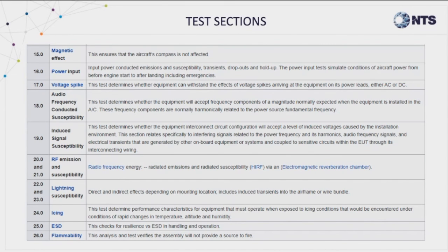I apologize. Is it too simplistic to state that mechanical products typically would be on the environmental side, salt, fog, humidity, temp variation, while the electrical components would be more an array of DO-160 testing relative to RF testing? The RF testing, yes. Anything electrical would be falling under the EMI, but the electrical also has to meet the mechanical requirements of the environmental tests, while a mechanical actuator with no electrical components would only have to meet the environmental conditions and wouldn't have an electrical cert as well. And so again, it's functionality and location that drive what tests are applicable.